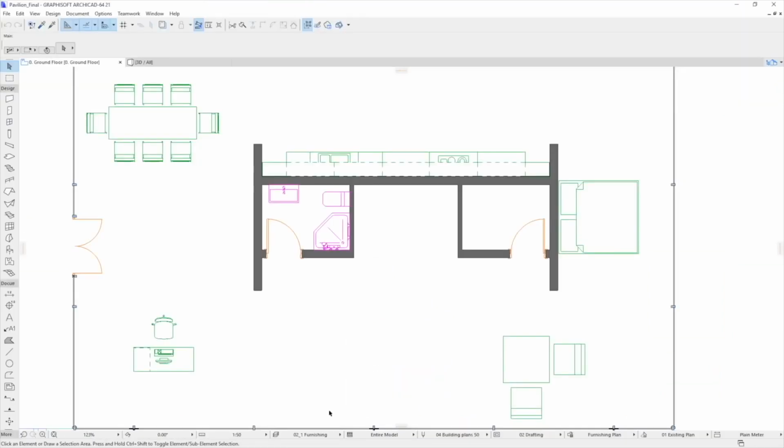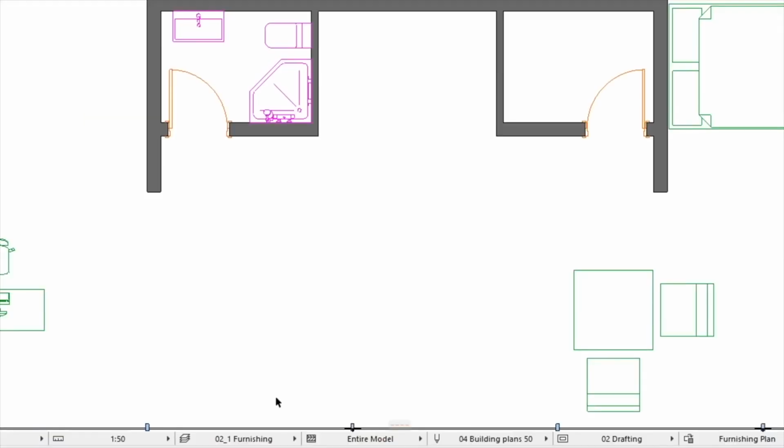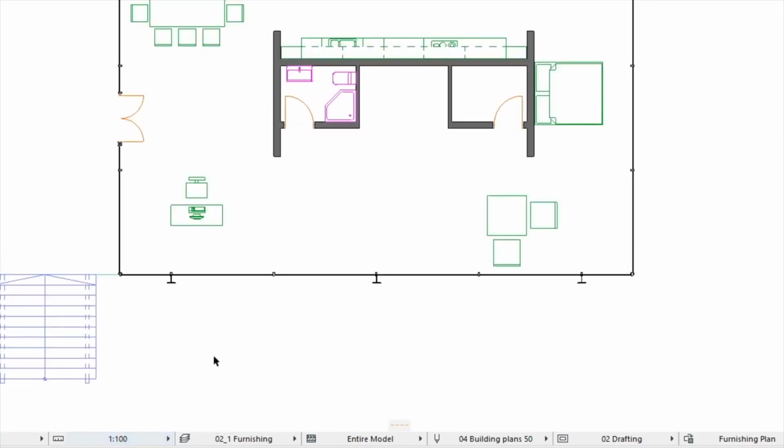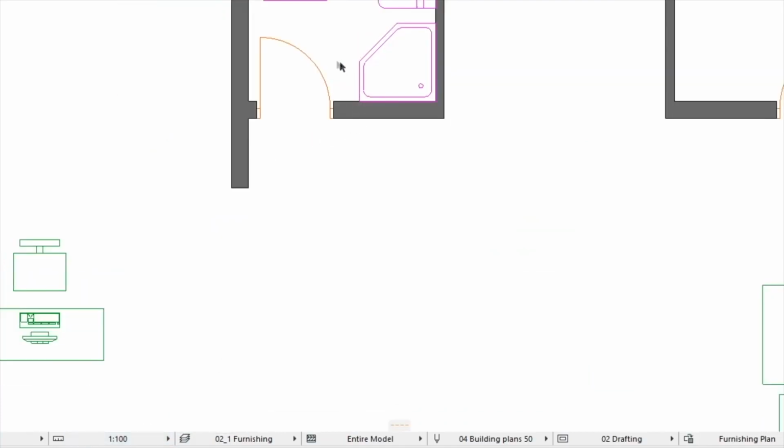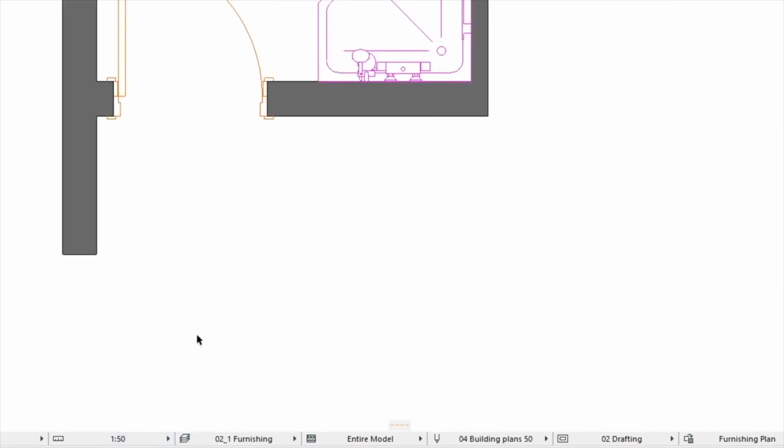The other significant difference is that the walls are displayed with a solid fill. There are 7 main factors for a view, all of which can be set using the bottom toolbar. The first factor is the scale of the drawing. For instance, plans that are submitted to the municipality for approval have a smaller scale than construction documentation. In ARCHICAD, objects like doors, windows, or other custom elements are scale sensitive. That is, their 2D representation depends on the current scale of the drawing.